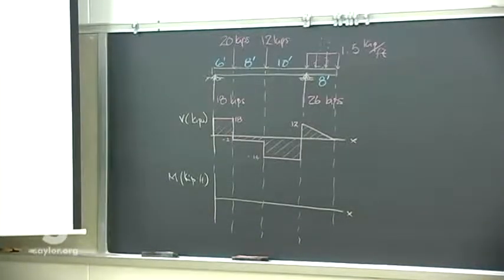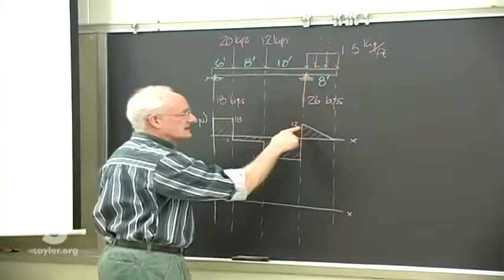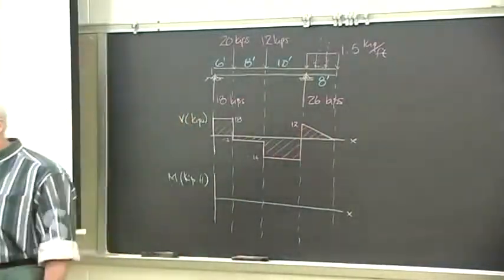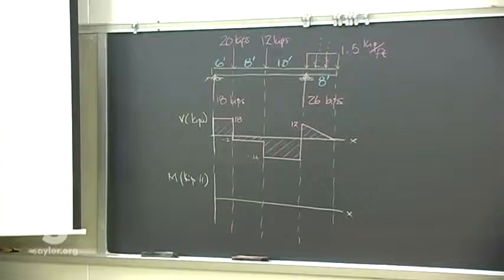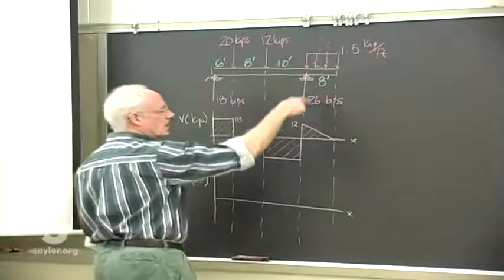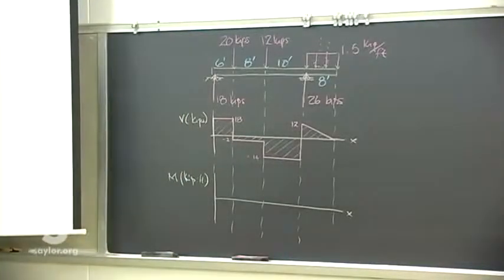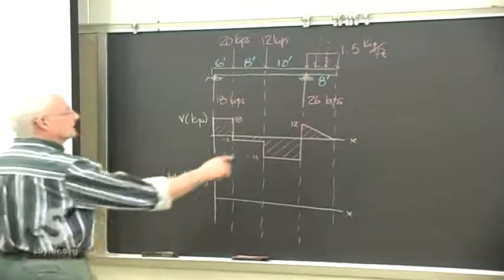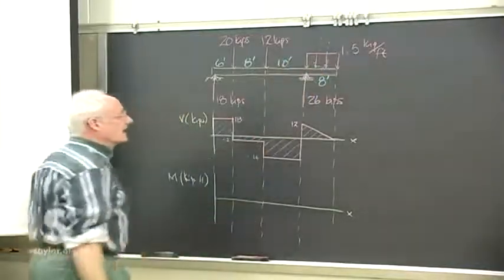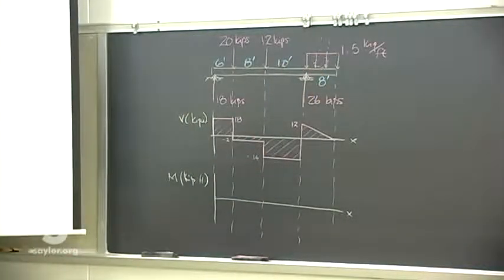And remember, take that point load out that we used for the distributed load here, because that does not apply on the shear diagram. I've seen over the years, a lot of students will leave that point load in there and then in some way try to incorporate it in the shear diagram. But that point load doesn't exist. It's not a real load. We need to get back to the real loading that we have, that distributed load there.